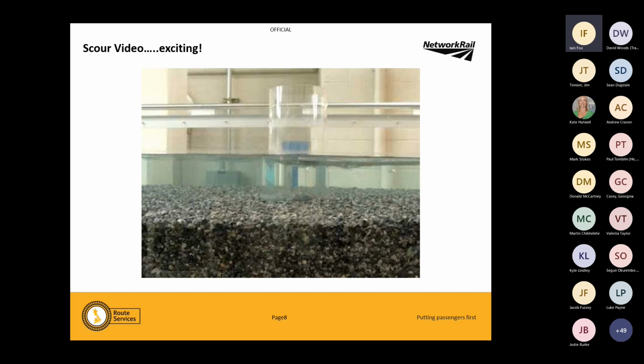We'll go again, 67 litres a second now. And now you can see there's an awful lot of material starting to move out of there. Now that standing wave, to me, is the signal that you've got scour happening at the base of that structure. I'm just going to rewind that one more time to 60 something, wherever it was. Quite a lot of sediment is getting moved from there. So hopefully that gives you a bit of a real world look at what is happening.